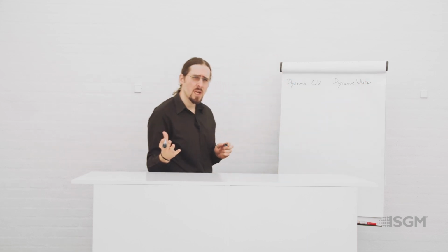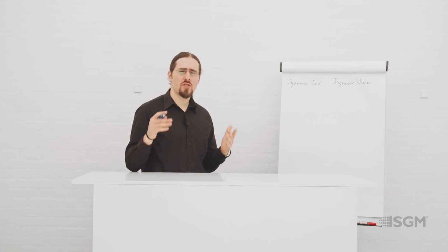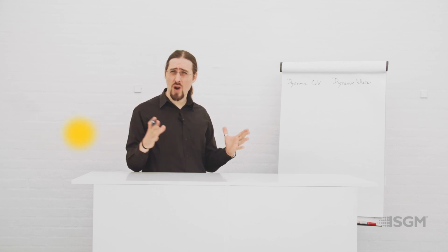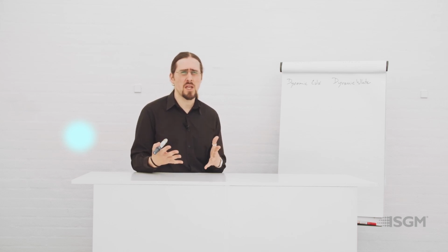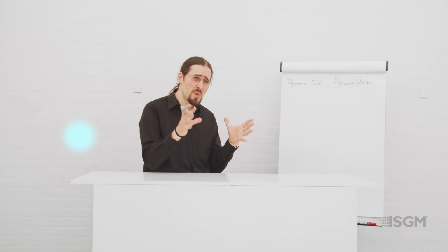That is dynamic color. A dynamic white is a different concept that is related to what we discussed about the LED arrays. In a dynamic white light source, you have the possibility of changing the color temperature of your white source. So you can do a more warm white, or you can do a cool white. And you can mix this depending on the application. So, for example, if you have a heritage monument, probably you will like to illuminate it with more warm colors, because that's how our eyes are used to.